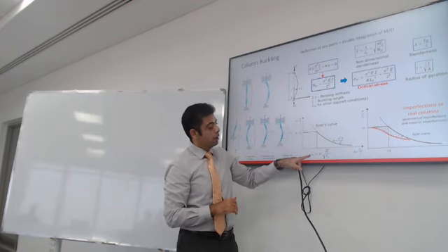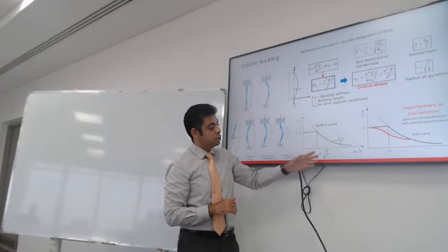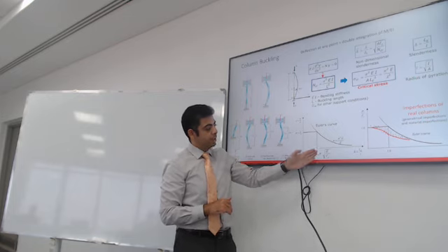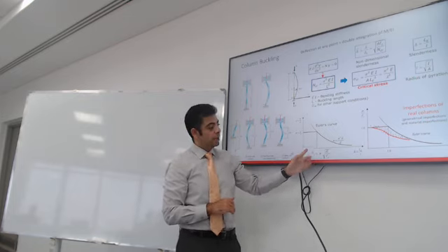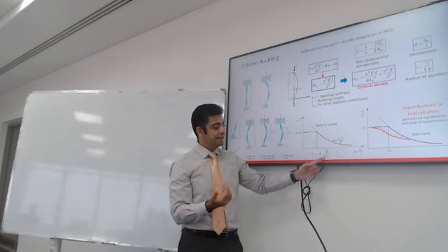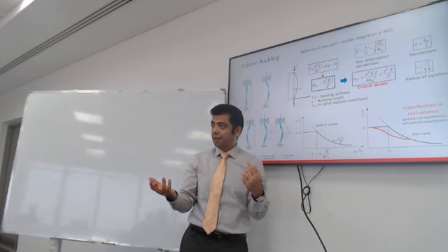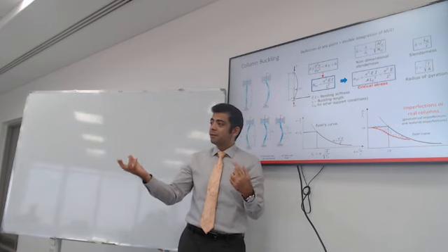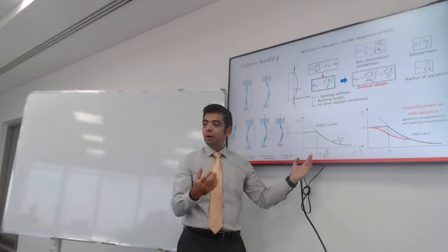If your lambda is shorter than a certain limit, which is lambda 1, you can get it from this formula. Modulus of elasticity is constant. Yield stress depends on the grade. So if you know the stress of steel you use, you can get lambda 1.